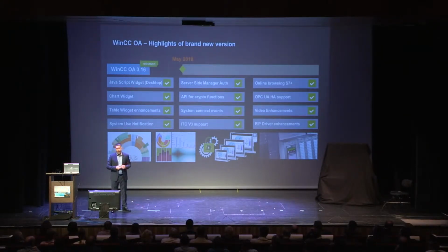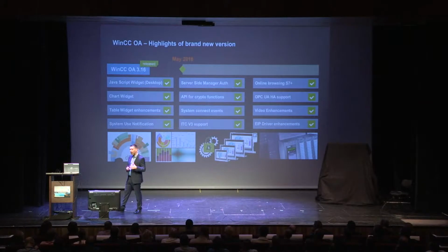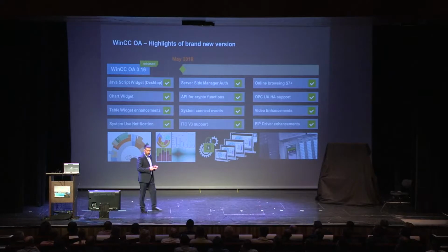Also a highlight inside this version for me personally are the System Connect events. What are the System Connect events? We created the possibility to subscribe, inside our control scripting, to system events like redundancy switch, data point creation, or log on or log off of a system.